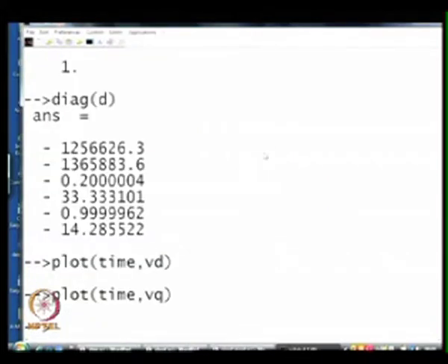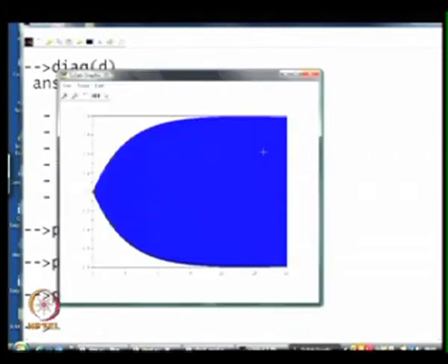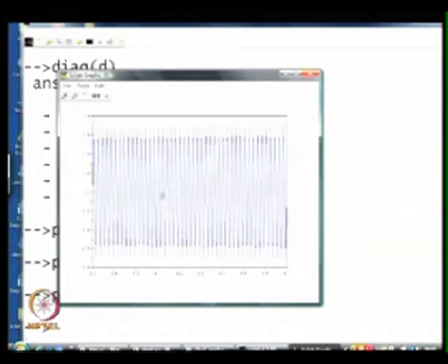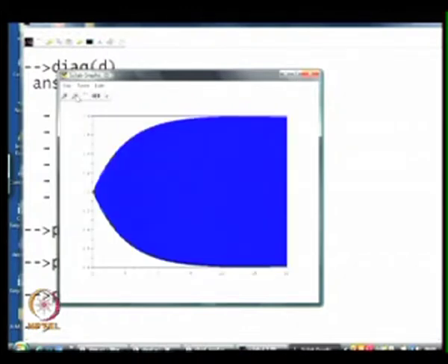Of course, from Vd and Vq, assuming that theta is equal to omega 0 t, we can obtain Va as well. So, if I plot Va, this is how it looks. Of course, it is a sinusoid. It reaches sinusoidal steady state. The envelope rises in the same way as Vq, but this is sinusoidal. If I try to zoom this, yes, this is in fact a 50 hertz sinusoid, since speed is constant. I will just unzoom this.